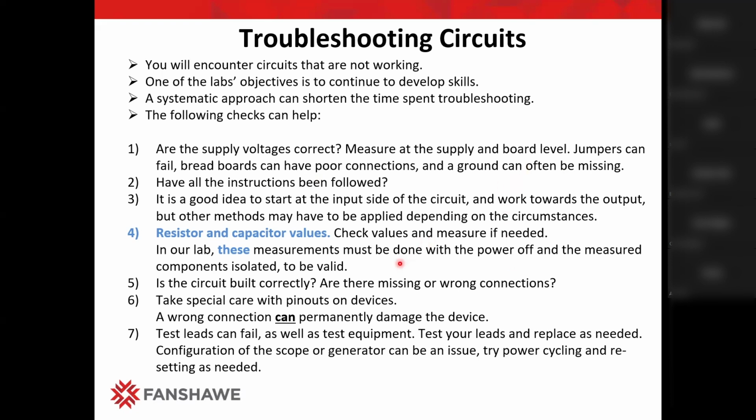Removing the component out of the circuit is a good rule to follow. Later on, if you are absolutely sure what you're looking for, then you can skip it. But if you want to check the resistance value, take it out of circuit, because then you can be sure that you're only measuring the resistance value of that resistor. If you don't take it out of the circuit, you're measuring the value of that resistor and all the resistance in parallel to it that is connected.